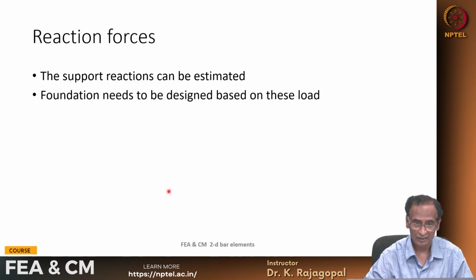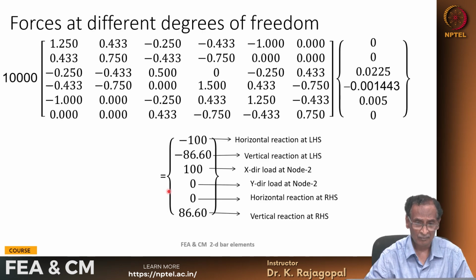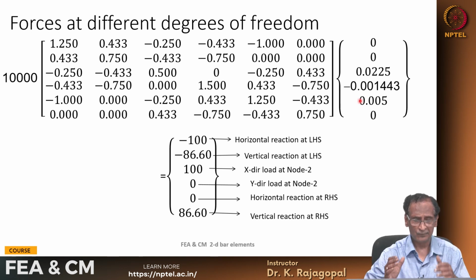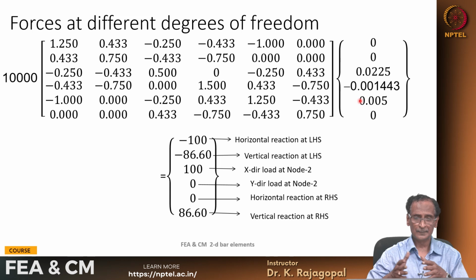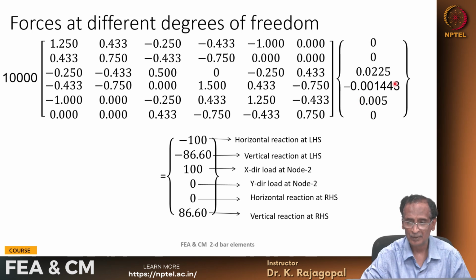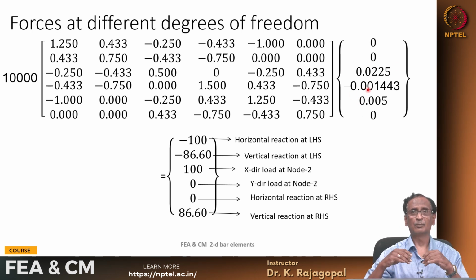So, this analysis has given us the displacements, and then the element forces, and then also the reaction forces. So, that completes our analysis. If you are not happy with these displacements, if you think these displacements are too large, then we can reduce them by changing the element properties.